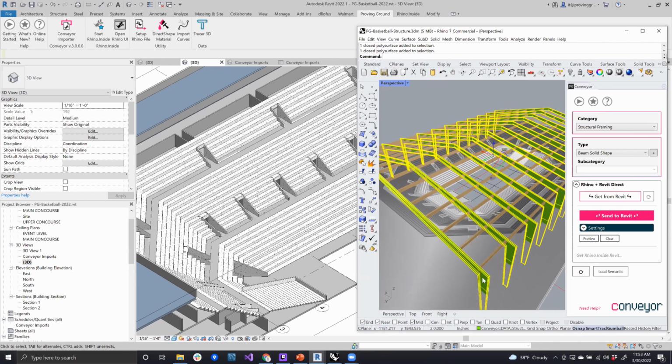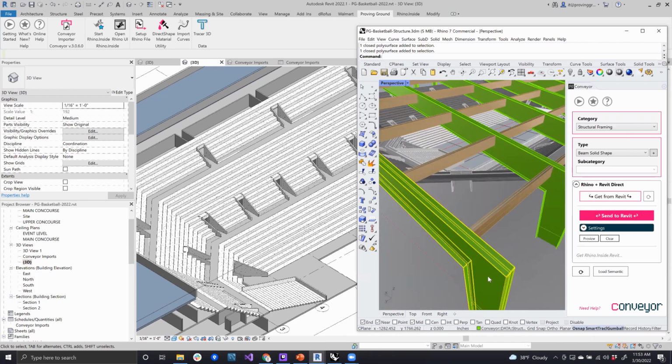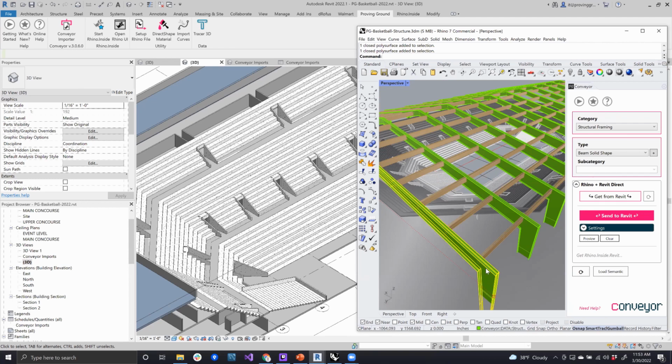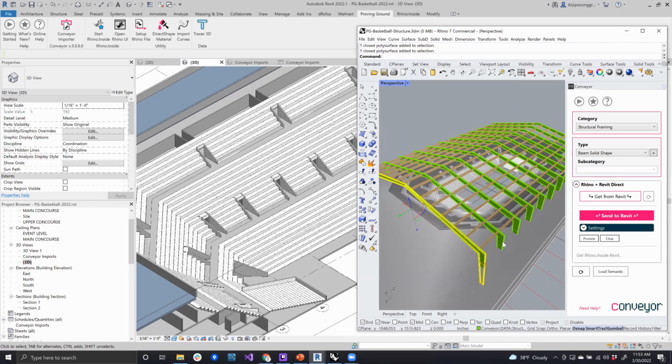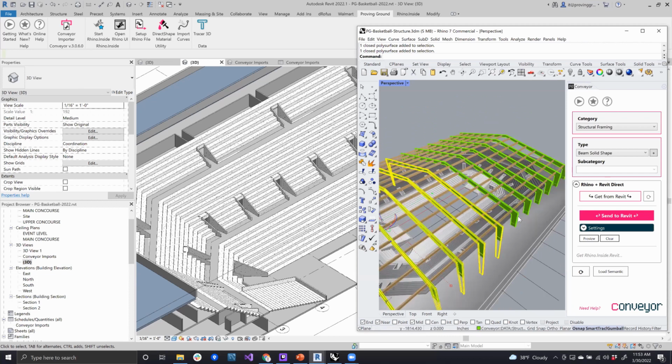Because this is a unique solid shape that's been defined, this is going to be another instance where that direct shape translation is going to occur. I'm then going to show you the way of doing more native structural framing using line-based. But for right now, I'm going to select, again, these objects. Should not have deselected before. And I'm going to bring these over wholesale back into Revit.